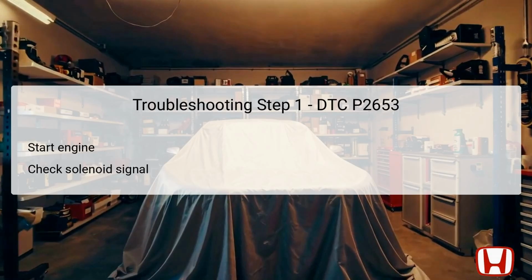This step is essential, as it lays the groundwork for subsequent diagnostic processes. By starting the engine and checking for the solenoid's operational status, you establish a base condition from which you can proceed with further inspections. In the second step of troubleshooting, you will inspect the rocker arm oil control valve.